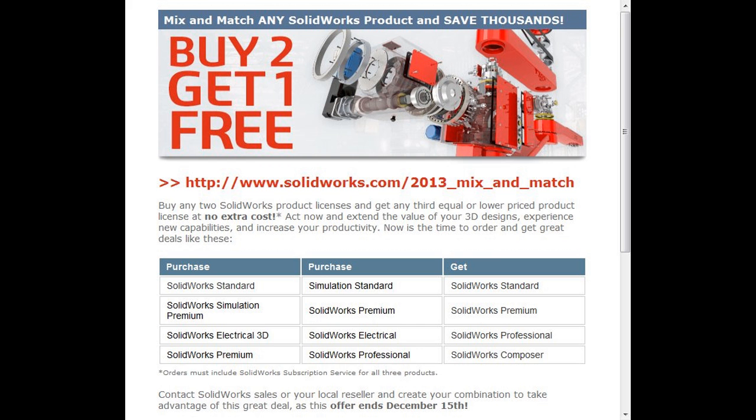If you have SolidWorks Professional, then you can double-click on certain items, and basically what's happening behind the scenes, like with fillets and some bosses, is we're invoking FeatureWorks to actually turn what you selected into a feature and allowing you to tug and move on it. So it actually does this kind of work behind the scenes for you. Try some simple models and see how it works, but it's actually invoking FeatureWorks behind the scenes to do that.